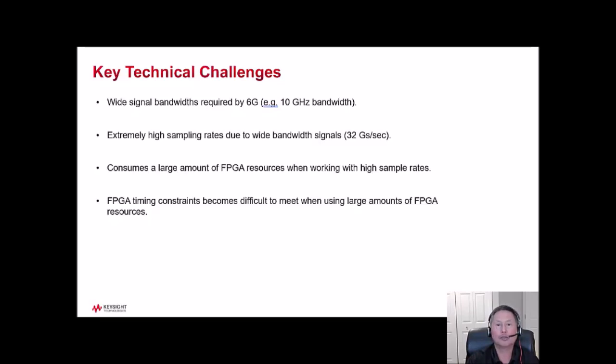When processing multiple samples at once, all of the FPGA algorithms are required to be parallelized. For example, to design an FIR filter that processes 80 parallel samples per clock cycle requires 80 parallel FIR filters. If a single FIR filter requires 20 multipliers, the bank of parallel FIR filters needed to process 80 parallel samples per clock will require 1,600 multipliers. This quickly consumes large amounts of FPGA resources.